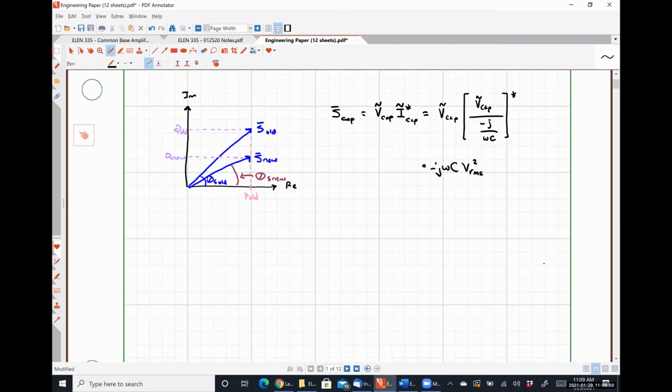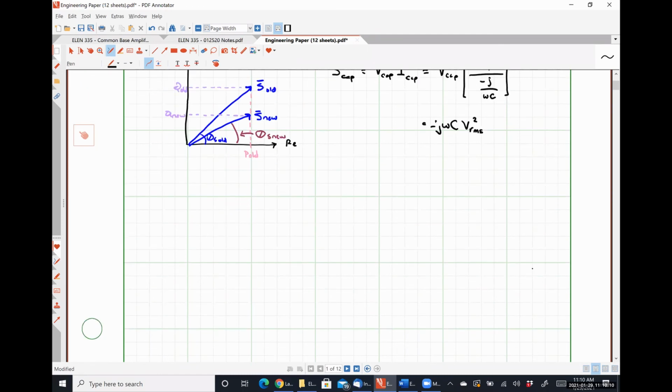All right, so now that we know why the capacitor is the missing piece of the puzzle here on how to do power factor correction, let's walk through the mathematical process with a simple example problem, okay? So let's say that we have a voltage source, and let's make it 600 angle 0 degrees volts RMS.